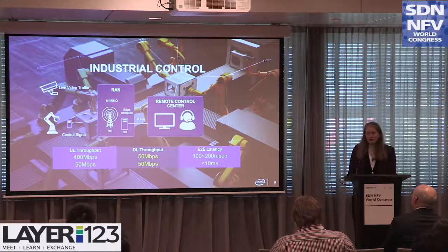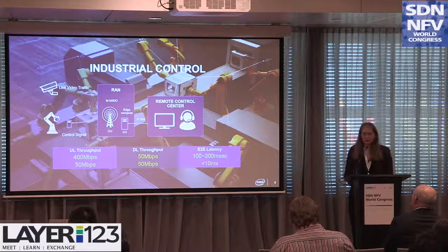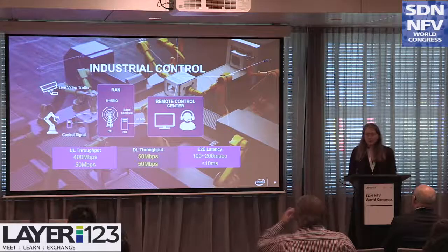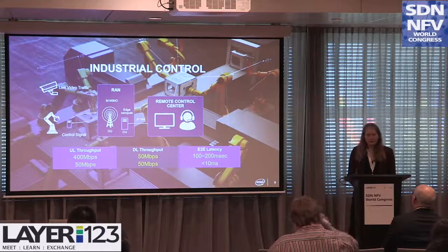It's kind of worth saying that if you're a base station physical layer designer, then you usually pick all the algorithms that you're going to use, in particular those uplink receive algorithms, based on things like your radio environment, based on the kind of traffic flow that you're expecting to get, and then do trade-offs between cost and performance. So if you're building something for a wide area network, then you want to choose quite generalized algorithms to suit quite a wide range of use cases and have all your base stations the same. But this industrial control is a specific scenario, and it's quite different. So we might want to choose different algorithms to get the best performance out of this scenario.